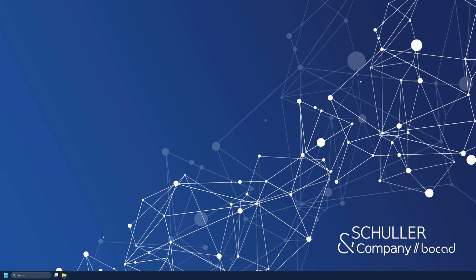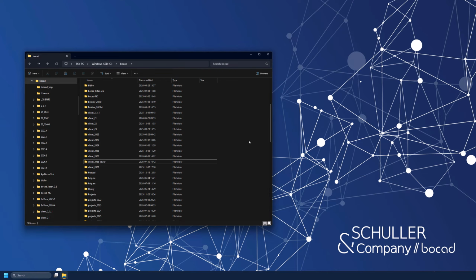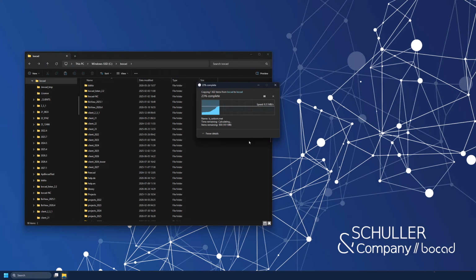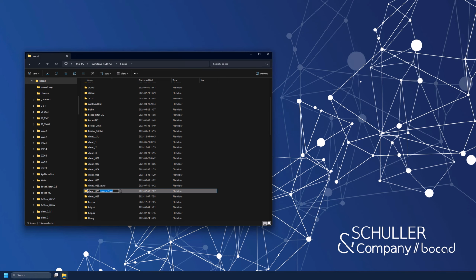If you want to set up a client for an Imperial environment, or you want to start working on Imperial projects, there are a few steps you have to go through. First of all, copy your existing client folder. Rename that client folder, for example, client 2026 IMP. And the other one, the original one, I'll call it MET for metric. That client then has to be activated.